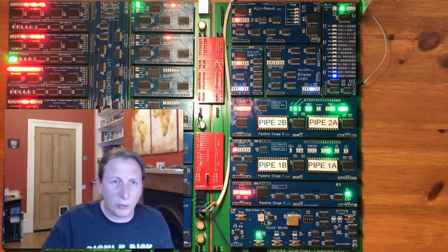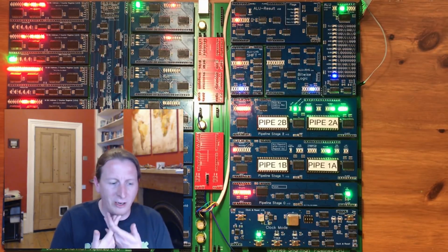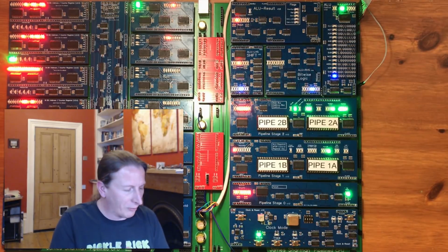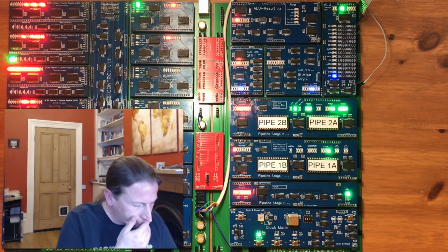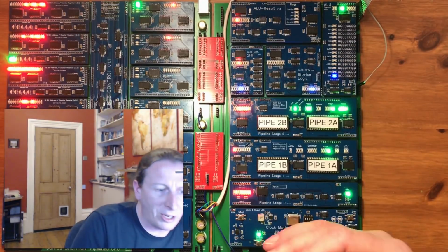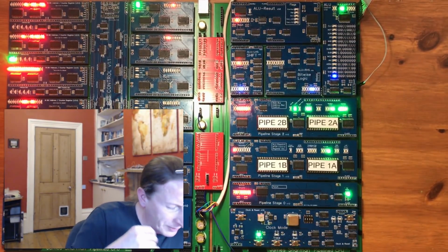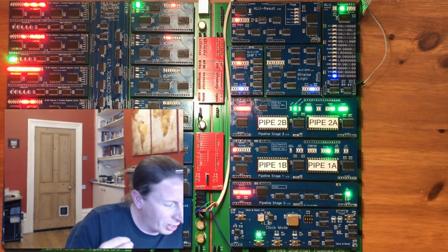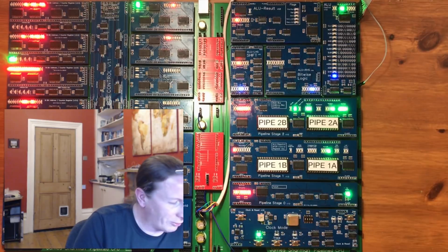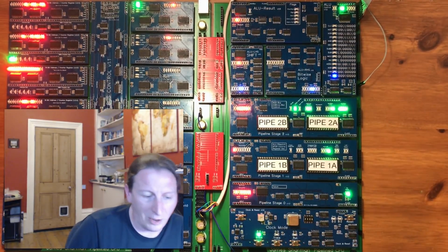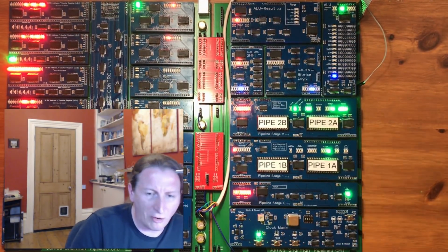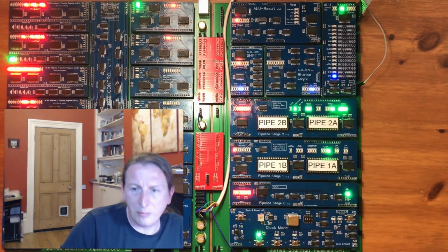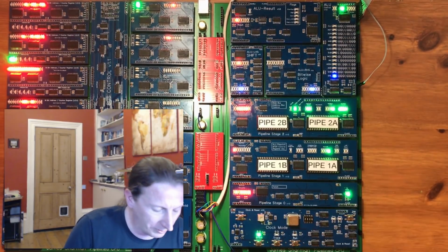Now, I can give you a very quick explanation of what is necessary to add interrupts to a build like this, and maybe that will give you an idea of why I made the choice. Now, the crucial thing about interrupts is an interrupt is a signal that comes from outside the processor core that will change the execution point of the processor to a routine that can handle that. And that means that the processor can react very quickly without whatever the running code needing to know it might need to react to that particular operation.